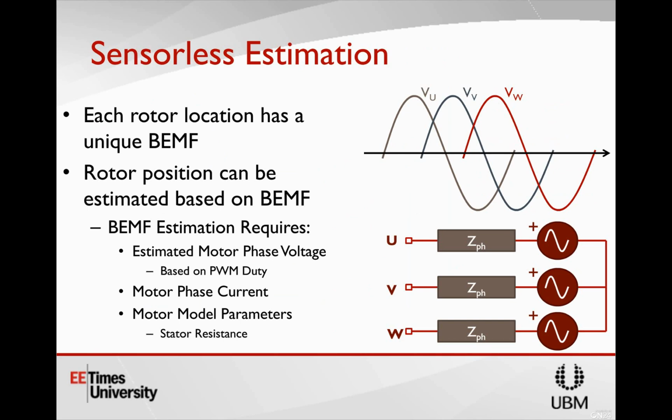And then once we have it, what do we do with it? By taking in the back EMF estimates that we've calculated based on our knowledge of the circuit electrically, since it's three vectors, we can represent it as two vectors, and then we can take the arctangent of those two vectors to figure out the angle of the motor. And so this is just one example of a fairly simple sensorless algorithm, and it's just the basis for a lot of different sensorless algorithms out there. Obviously, since this is a simple example, they only get more and more complex and more involved, and can consider a lot of other models and a lot of other things in your circuit that will improve this model.